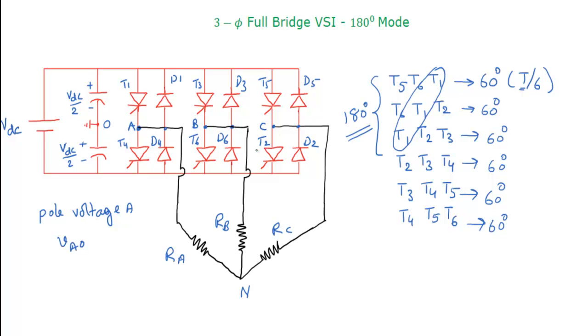As we know, in a balanced three-phase system each and every phase voltage and line voltage will be 120 degrees apart. That's why we are not going to discuss each and every voltage waveform. Only one voltage waveform is sufficient, and if you want to know the remaining, we need to take the 120 degree phase shift. Likewise, another voltage is the phase voltage, which is the voltage difference between this one and the neutral point. So A and N is phase A voltage, and the potential difference between this point and this point indicates the phase B voltage, likewise phase C voltage.